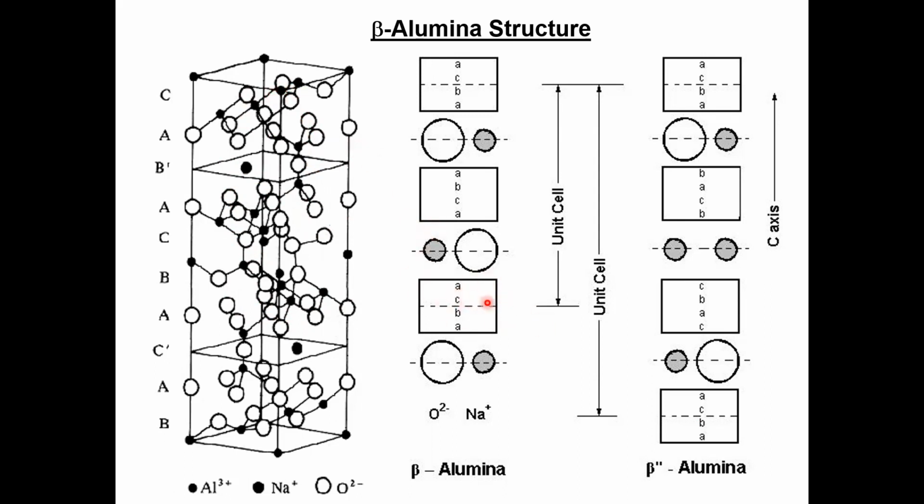I'm basically showing schematically the 4 layers of aluminum and oxygen in the spinel block, and the conduction plane, where you have your transporting species. So this would be for sodium beta alumina. This would be sodium, this would be oxygen in the 2-dimensional conduction plane, and then spinel block, conduction plane, and so on. So the conductivity happens on this 2-dimensional layer. So unlike silver iodide, which is a 3-dimensional ionic conductor, beta alumina is a 2-dimensional ionic conductor. And it has implications for processing of the material.